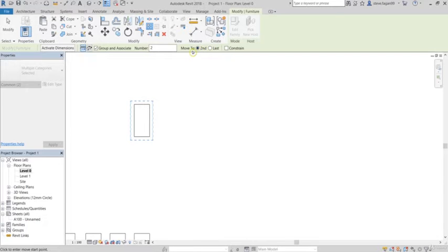Next is how we start the array. Whether we start by placing the second component or the last component. Once we place the second component, then the array will continue on after that. If we place the last component, everything will be arrayed inset to that. Again, we can constrain them if we need to. So I'll do a quick example here.